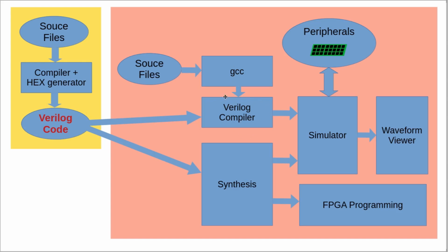This Verilog compiler is going to generate some files that I can run in my simulator, VVP. While the simulation is being run, I can interact with my peripherals. The code added to the source file can do this interaction, or I can interact directly with the keyboard. After a certain amount of time, the simulation stops and I can have a look at the waveforms that are generated.